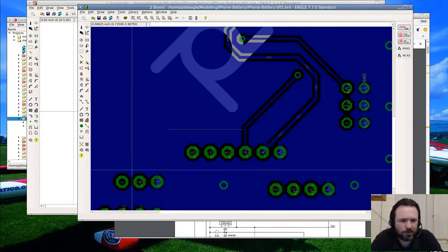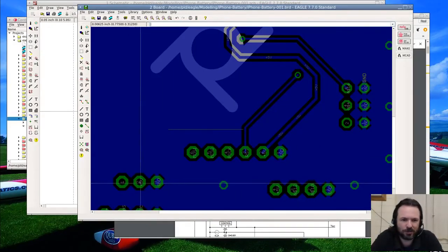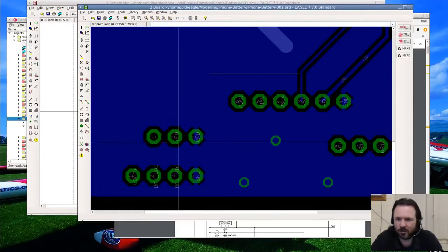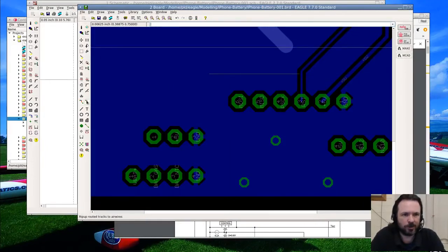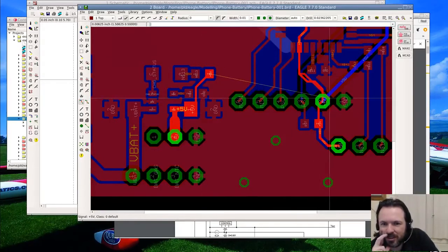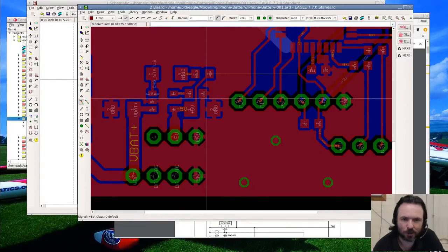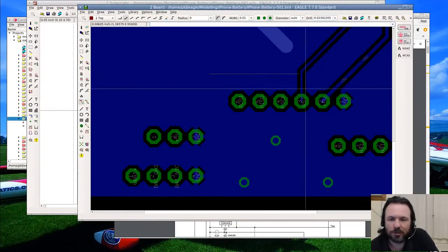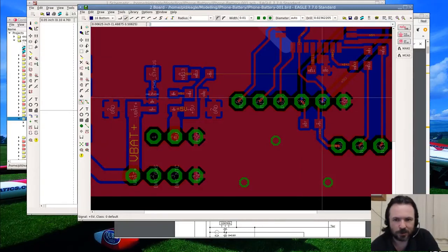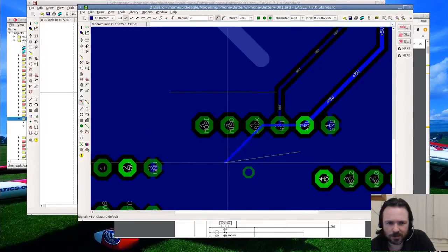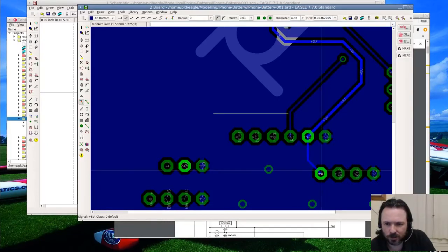One thing I have got frustrated with is that if you've got a trace like this and you say want to start it from here because this is a 5 volt that it wants, maybe someone who knows Eagle better can tell me how I can make it so it starts from here. Because at this point I haven't found a way. Alright. And as it is, it looks like I just need to go from there to there. And I'll do that on the underside. So usually the way I have to do it now is I'll take a little piece out of there and use that as my starter to come over here. So like I said, there is probably a far more efficient way of doing this. I don't know it. And I did that wrong. Bottom layer. That's it. That's interesting. Why are you highlighting?